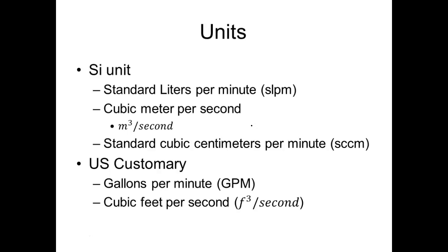The same thing is true in our atmosphere too. Underwater, the deeper you go, the more pressure you have. Well, same thing's true for air. The lower you go, the more pressure you have, right? So if I was just to use something like this, my flow rate meter would indicate something different in Boulder, Colorado than it would down in Gulf Shores.